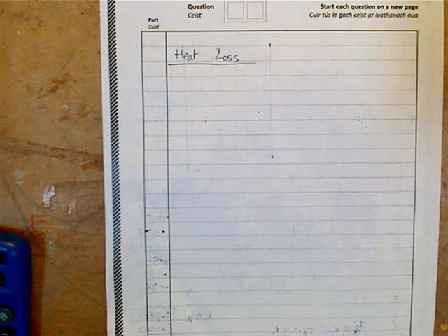Now, if we were doing that, what would today's external wall U value be? Does anybody know? I think it's 0.15. I could be incorrect on that, but you can see that the 1970s wall has a really high value, 1.8.